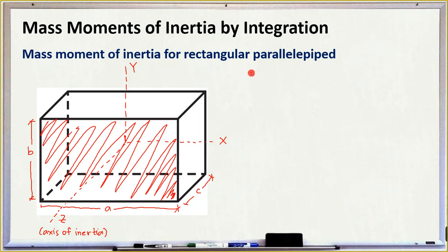So applying the generalized formula for a regular prism, again, the moment of inertia of our rectangular parallelepiped along the z-axis is equal to the mass of this rectangular parallelepiped times the polar radius of gyration squared of its cross-sectional area. No? But Kp squared again is the ratio of the polar moment of inertia of the cross-sectional area of this rectangular parallelepiped divided by its cross-sectional area.